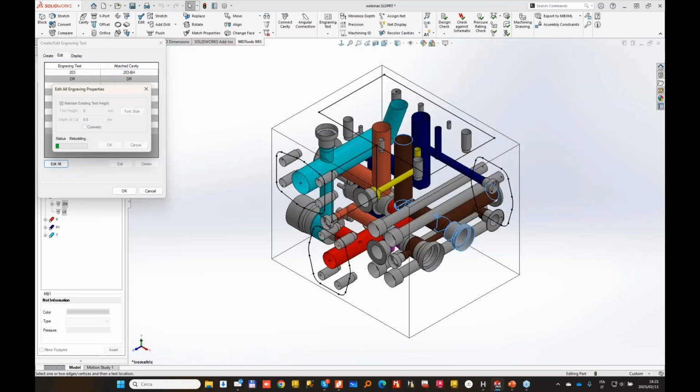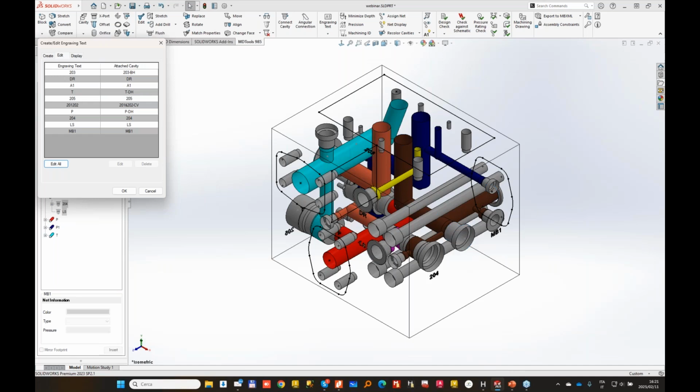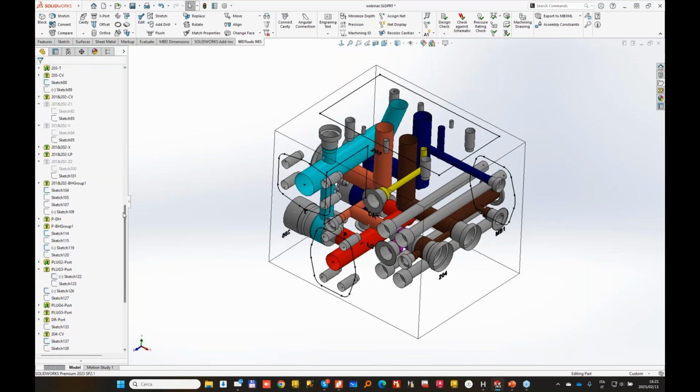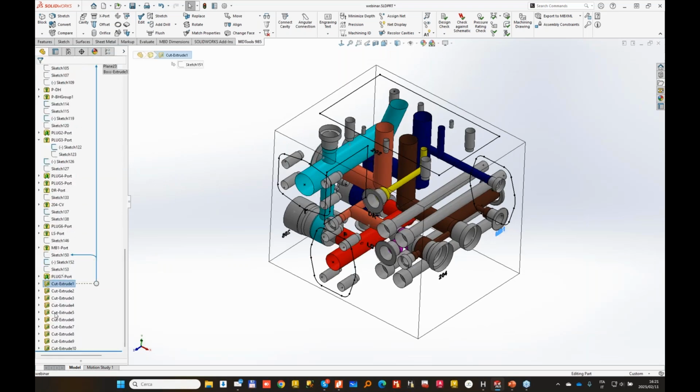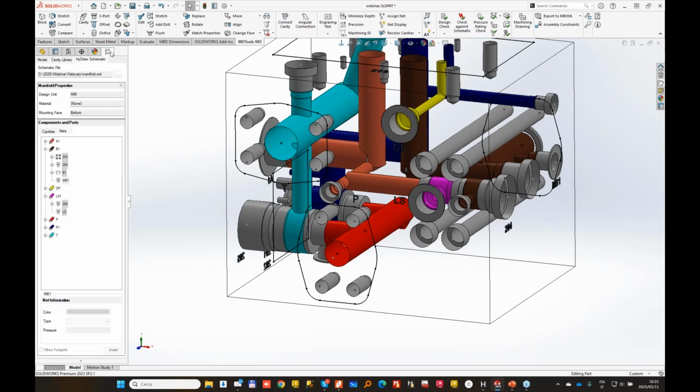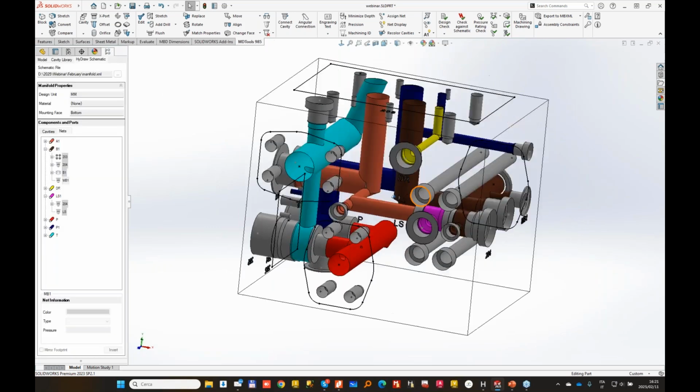In the past, MDTools was using a function of SolidWorks called wrap text wrap. Now we use extrusion. We found it more efficient in terms of speed. So you will see a big improvement. As you can see, it's cut extrude for all, but this will have an impact in design speed.